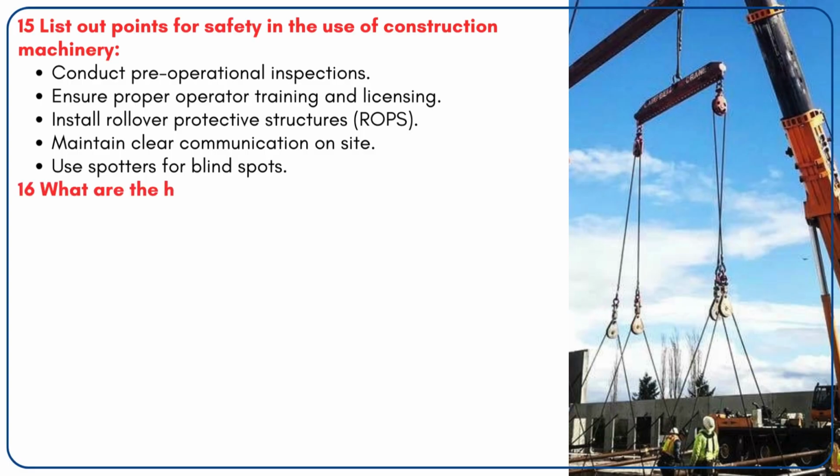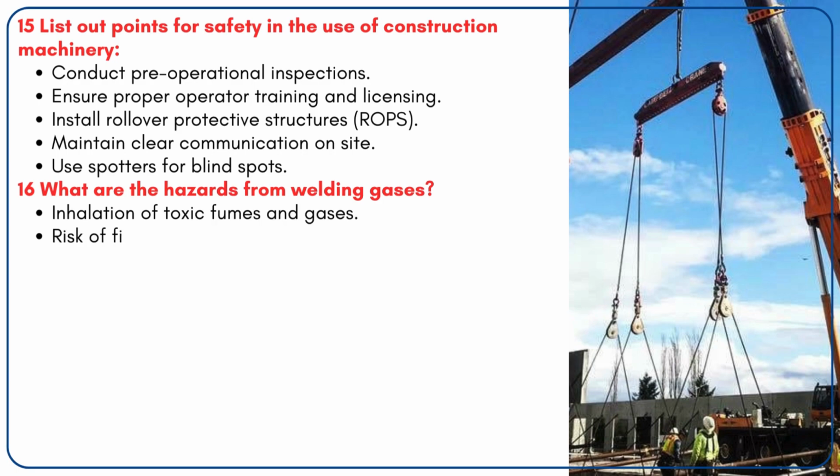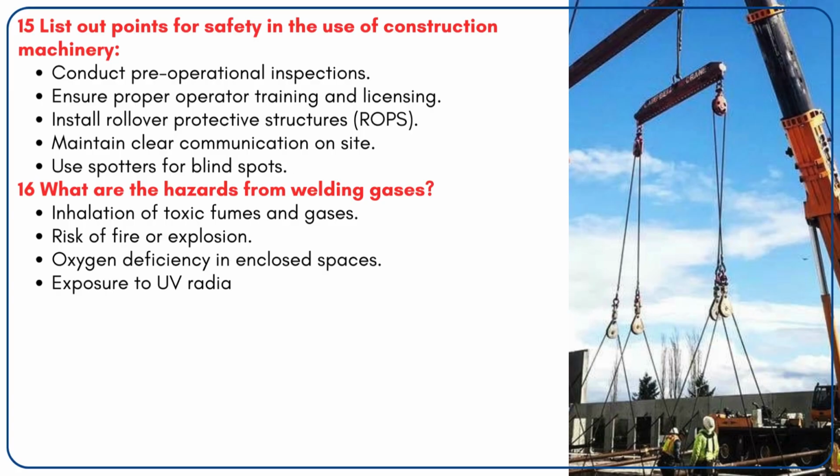16. What are the hazards from welding gases? Inhalation of toxic fumes and gases. Risk of fire or explosion. Oxygen deficiency in enclosed spaces. Exposure to UV radiation causing eye and skin damage.